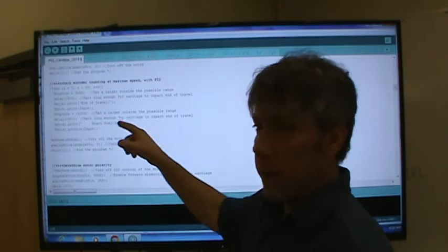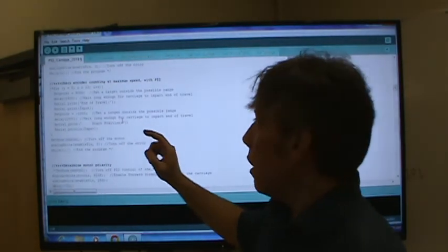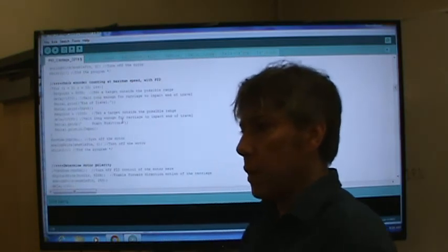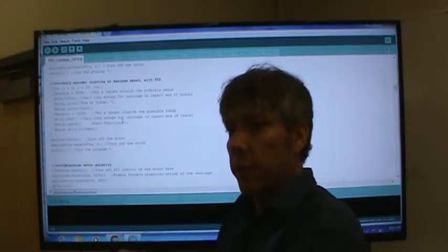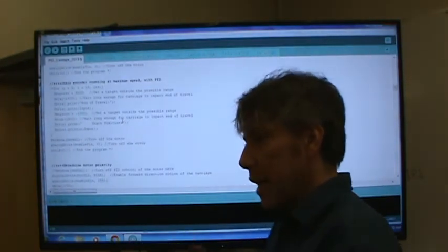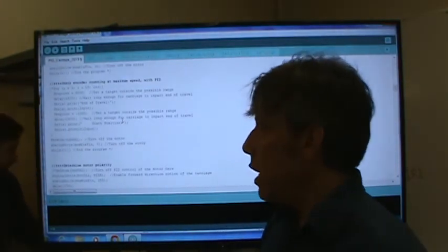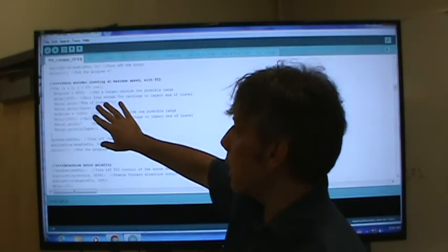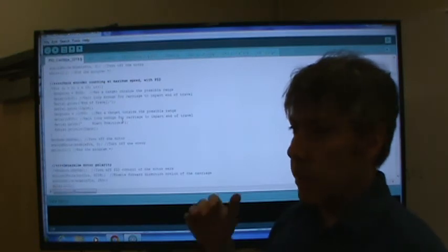Well, this is where I found I was losing counts, because while it could keep up before by just turning the motor on and moving, if there was another bit of code, the PID loop, running 1,000 times a second, trying to check and see if the carriage had reached its position, it simply could not keep up. So what I did with this code is I played around with my PID loop frequency, and that's where I started reducing it from 1,000.